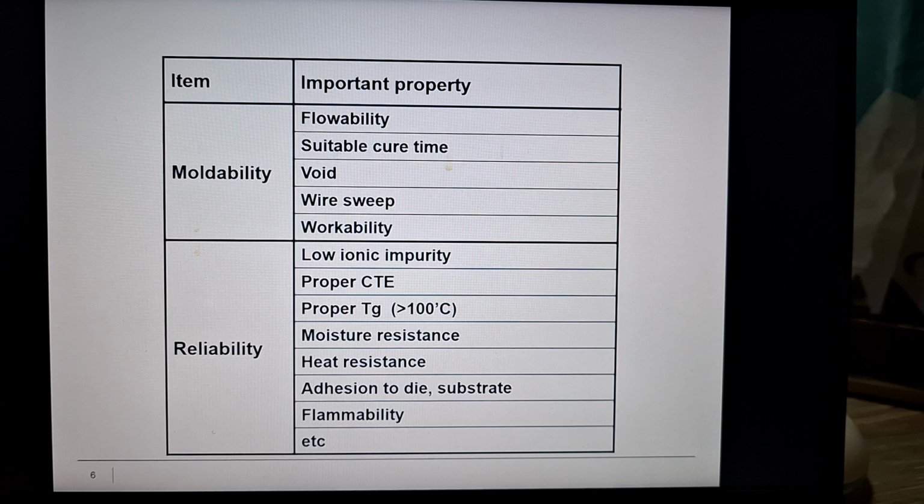And then of course some of the reliability concerns require a very good material that can withstand moisture. So it should have very good moisture resistance, including heat resistance. And of course, when you apply high temperature, high moisture, high pressure within the package, you also need very good adhesion. It weakens the adhesion when you apply pressure. Something like you're clinging to something and there's pressure applied on you. The worst thing that could happen is you lose control of holding all the material.